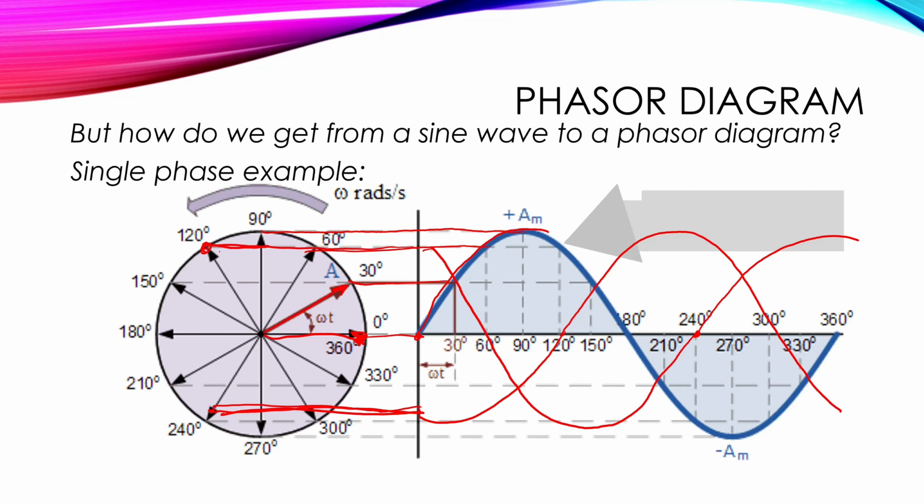Okay. And so is it 120 degrees? No, that's just a representation in time. What we're saying is that this entire cycle right here, from here to here on A phase, is 16.6 milliseconds. Okay, so that's one cycle. That's one rotation that we're going to represent. Where would C phase be if it was in a rotation? Well, at that point in time, it would be 120 degrees apart, you know? So that's what we're saying.